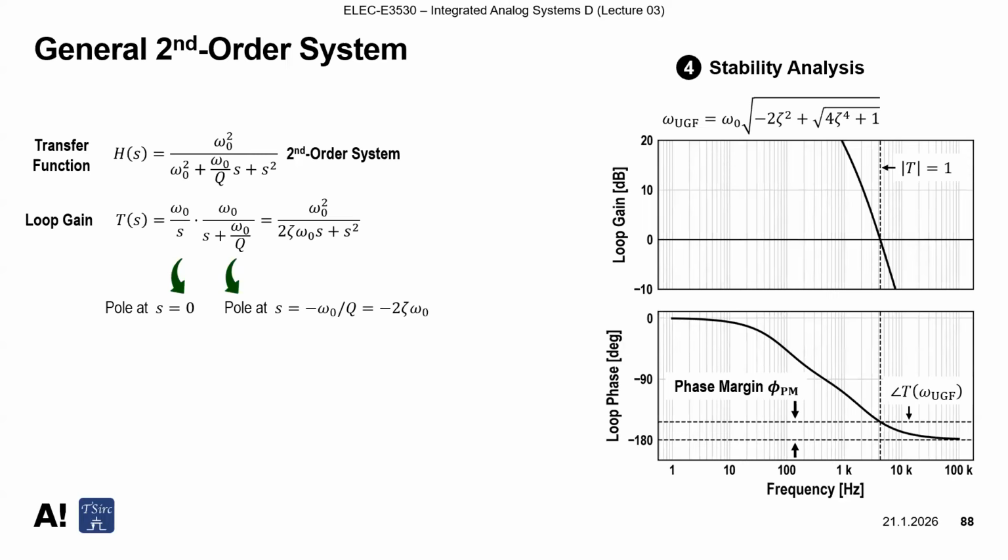That is another key point to figure out to calculate our phase margin here, right? So if we can find this phase as an equation, then we can derive our phase margin by simply getting the difference between this phase value and minus 180. Then we can get the phase margin, right?